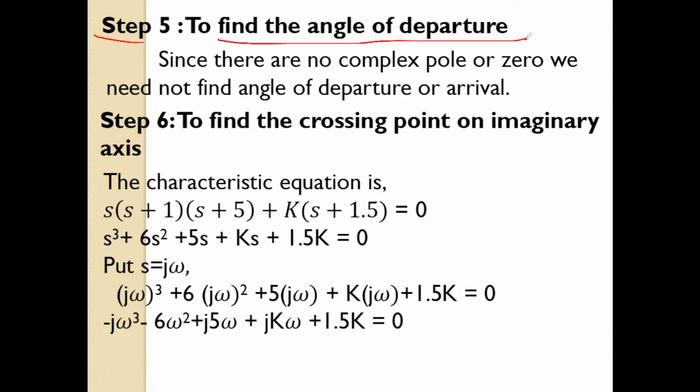Therefore simply go to your root locus. Of course there is a pole here, there is a zero here; definitely root locus will start from P3 and end at this zero. Next there is a pole P1 from where root locus will start, from P2 root locus will start, and there is a breakaway point. From the breakaway point, root locus will travel from P1 and follow the path of an asymptote. No need to worry about the imaginary axis, because the k value we have got is negative. Another root locus will start from P2 and follow the path of the other asymptote.